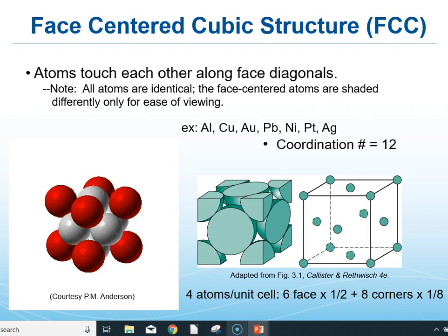These are unique in that a face-centered cubic is a close packed structure. Hexagonal close packed and face-centered cubic are the 2 densest or most volumetrically dense crystal structures that can be achieved with a single atom, and generally the densest that can be achieved, period. So these also tend to correlate with higher density. Definitely you see lead there and platinum being dense. Those also have high atomic weight, but it's another contributing factor.